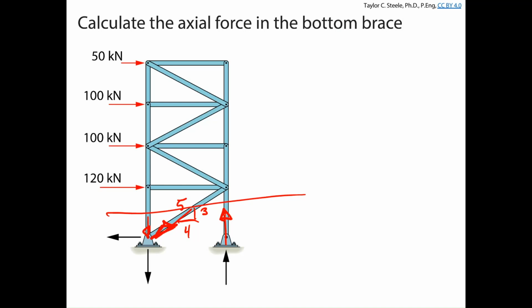How would we figure out what component of force that brace needs to resist and ultimately what that tension force would be? Sum of the forces in the X direction, right? We did this on Monday, except vertically. Here, if we sum the forces in X, calling to the right positive, that's 0. We have the X component of the brace force to the left. That's going to be whatever that tension force is.